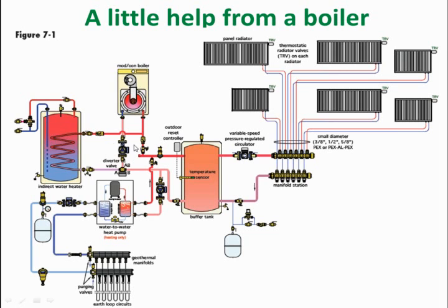So now what we're doing here is tying it in a way that it's got the ability to make domestic hot water with an indirect tank. So there's the ModCon boiler with a little 3-way diverting valve that can cover the domestic water load, and we still have the ability to put some heat in that with a desuperheater also from the heat pump. So that could go directly into the potable water of the tank from the desuperheater, and then we've got the ability to heat that tank with the boiler if the heat pump doesn't happen to be running.